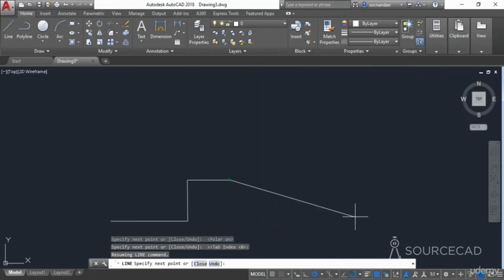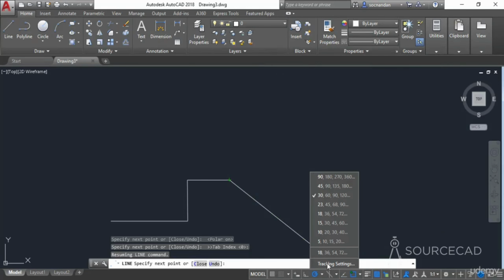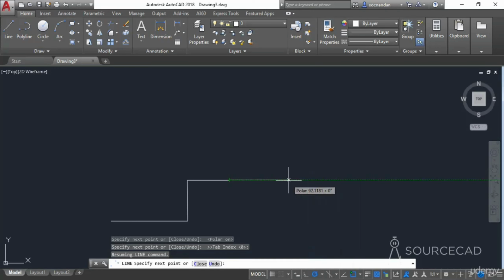So let's now click on OK, and now click on this arrow again, and you'll see that here we have this 18, 36, 54 and 72 angle. Although currently you won't be able to see the exact 17.5 degrees because precision of angle is set to 0, and we need to change that precision value in order to see the decimal points. So I'll just change that value.